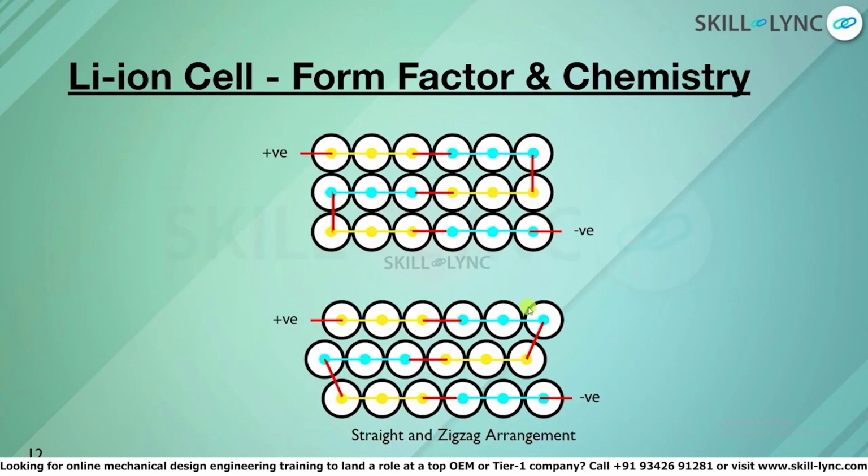Now we talked about flexibility of the cylindrical cells. Here we would see how the flexibility of the cylindrical cells can get affected and what are the advantages in those arrangements of the cylindrical cell. Now first one is a straight arrangement. We could see all the cells are arranged one beside the other. Now when I said there's an area loss, I am talking about this area. So this area is nowhere to be filled. Now how effectively we put the cells, we reduce the gap between each other and even the package. This is some area which you definitely lose in common.